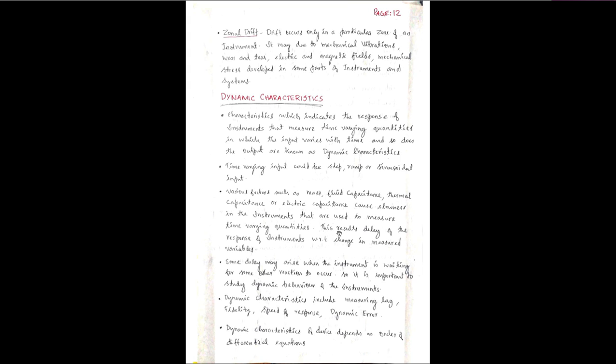So it will be making that instrument respond a little bit slow. This results in delay of the response of the instruments with respect to change of the measured variables. Some delay may arise when the instrument is waiting for some other reaction to occur. After that only it will be responding to that. So it is important to study the dynamic behavior of the instruments.